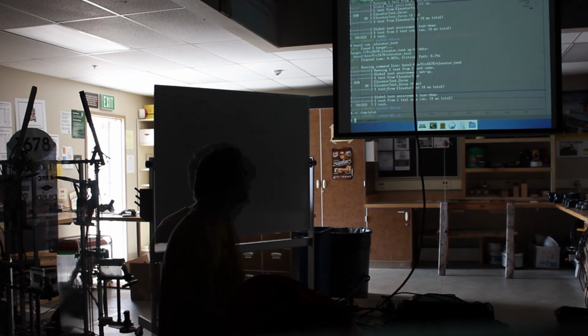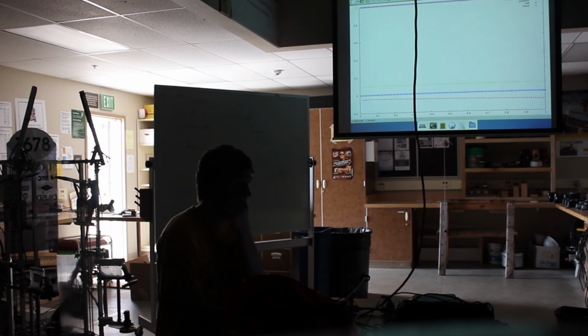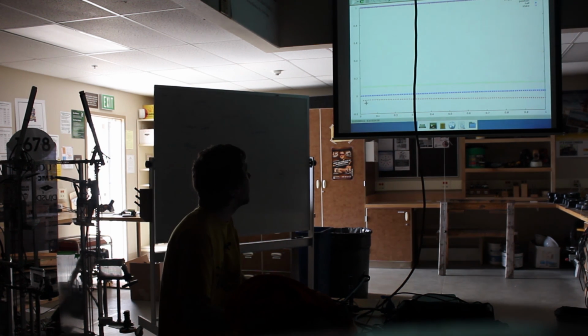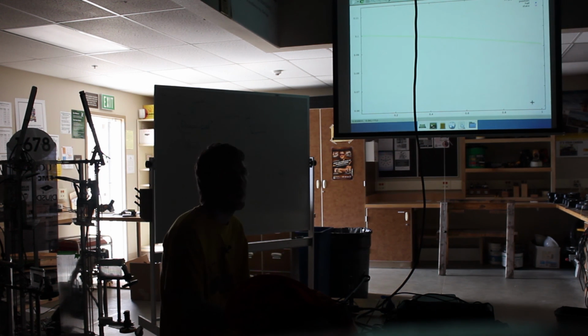So let's try it. Oh, we're in state 1. So we're in our lowering state. And Hall effect never actually triggers. And the position, I think that's slowly going down. I think we need a larger peak, maybe. Oh wait, this is a really small time scale though. It's coming down. Yeah. We're supposed to move 0.05 meters per second. So yeah, it's probably not a stiff enough loop yet. So we should crank it up. Crazy. Let's resume this in the next session.